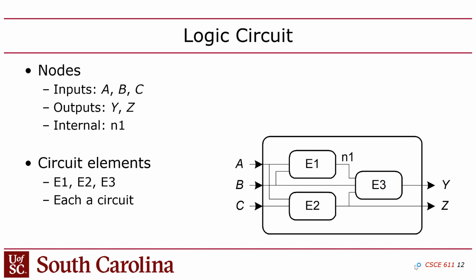You see, so you have a mixture, you have inputs and outputs, and then you have internal signals. Internal signals are ones that are hidden by that module when you use it. It's abstracted out, essentially. The N1. The only time you see N1 is when you're working on that design. When you use that module in another design, of course, you don't see N1. It's hidden, right? But you do see the inputs and the outputs.